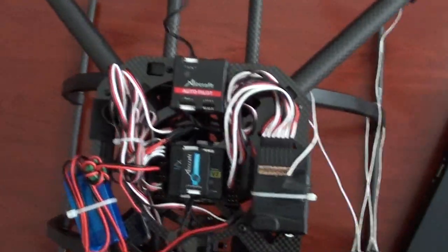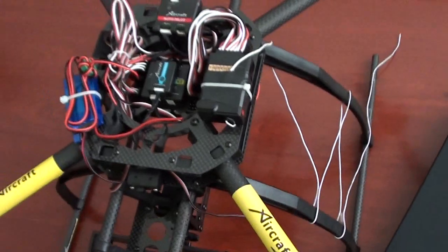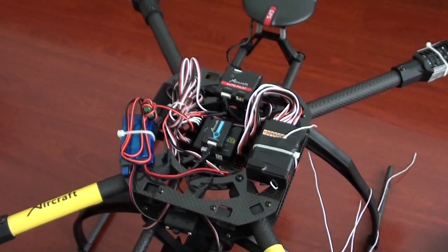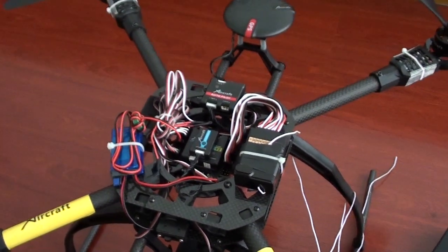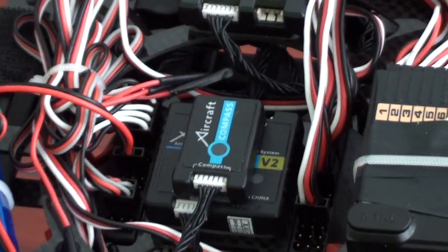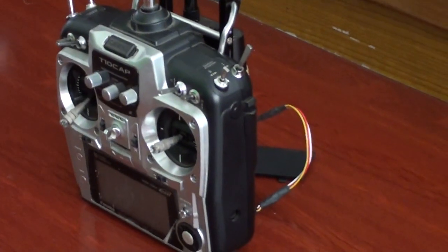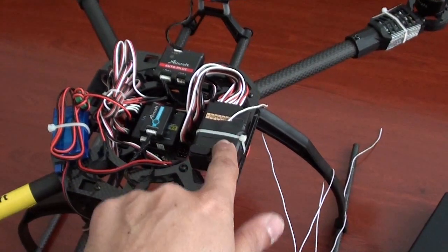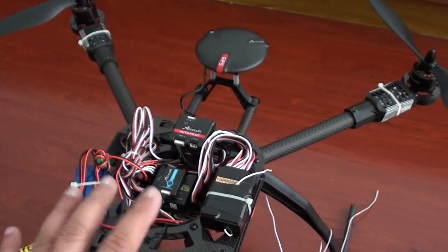Okay, here's the finalized setup. I'm bound to use the Futaba 72 MHz because of the channels. I have the only 7-channel receiver here. So right now I can use the attitude hold flight mode, GPS hold flight mode, and auto return to home flight mode, but I cannot use the carefree flight mode using compass. Anyway, later I will order the Futaba FASST module for my T10 and 2.4G, and order a 10-channel receiver, and then we will check all the functions of this quadcopter.